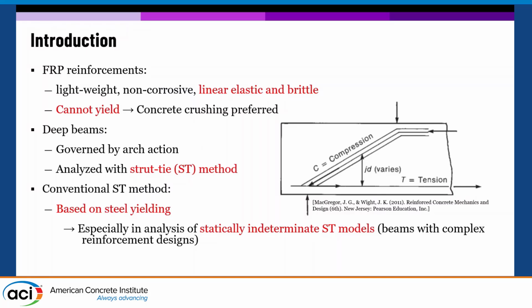All of this I actually already said. It's in points here. So we did figure out that statically indeterminate strut-and-tie models can be used for analysis of these beams if you make certain assumptions. Why statically indeterminate? Because of the flow of stresses, you need a lot of members, so effectively the truss becomes statically indeterminate.